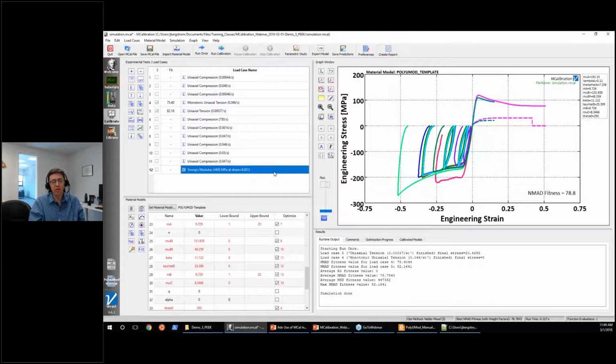And the viscoplasticity in this model too can be calibrated uniquely from uniaxial data only. So there is no need to do plane strain, biaxial, or any of these other complicated loading modes if you don't want to. It's okay to do it, but it's not absolutely necessary.